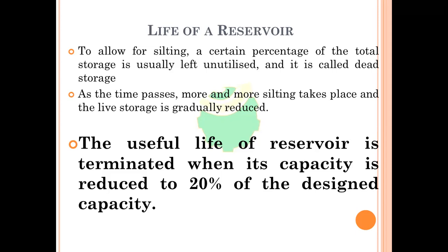So that time is called the life of reservoir. Due to silting, the capacity of the reservoir is reduced up to 20% of the designed capacity. The time taken for that reduction is called the life of reservoir.